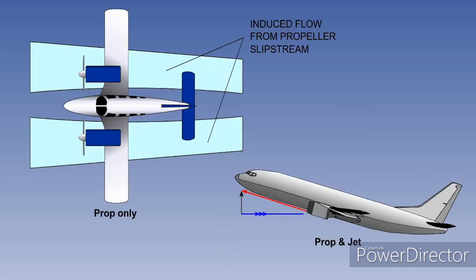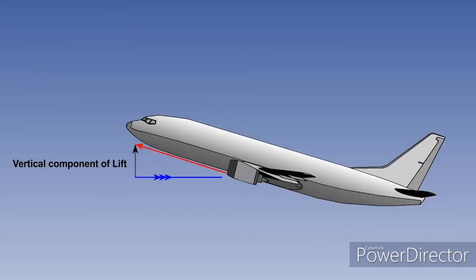Regarding engine thrust, the EASA Regulation 25.103b states that VCL max is to be determined with zero thrust at stall speed, and it is assumed that the aircraft is supported entirely by lift. If thrust is applied close to the stall, the nose high attitude will produce a vertical component of thrust, which helps to support the weight, and less lift is required.